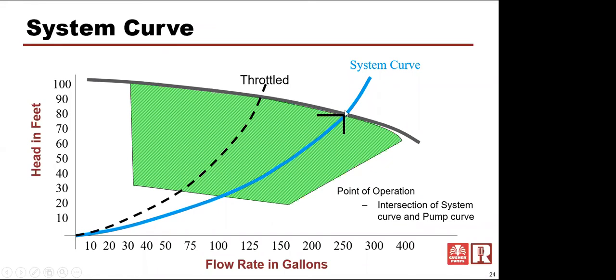Remember I said when we had 3 pumps running in unison pumping into a header that we had calculated that we would have so much flow in that system. Well, if we shut off those other pumps, what we're doing is creating that open system, and that pump is allowed to run way out on the curve, which is generally a very bad thing. We're going to get out in areas where we're going to get cavitation. We're going to get out in areas where we have a lot of shaft movement and bad things going on in that pump.